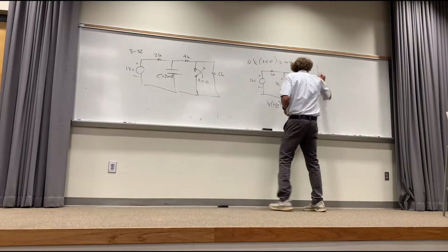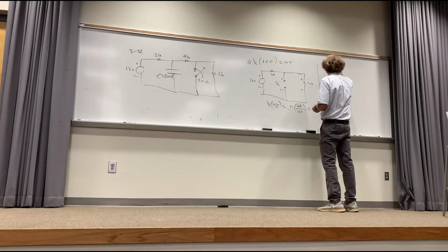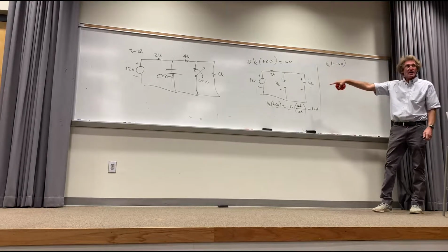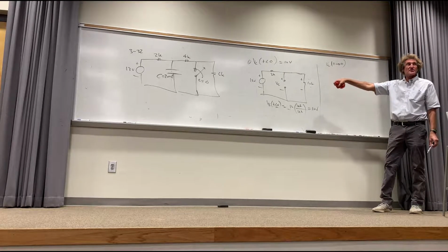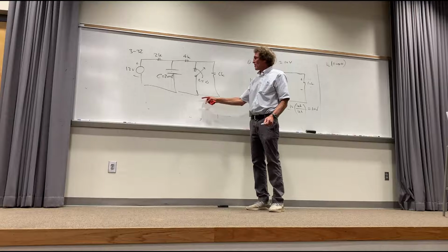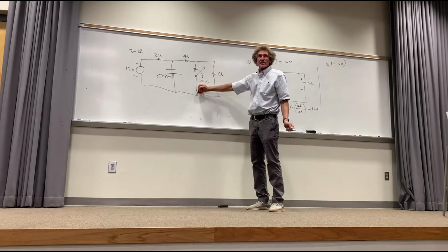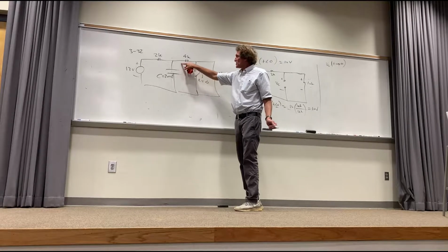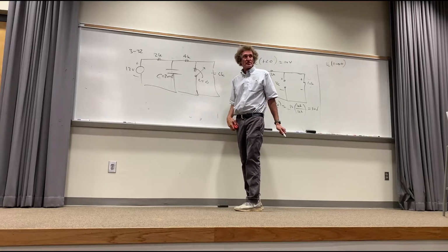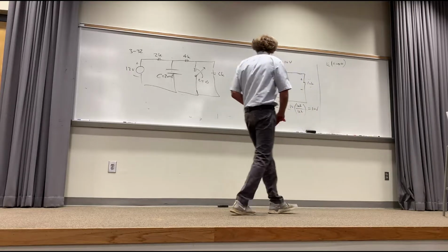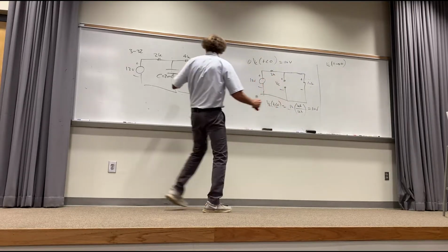The next step is to find the voltage as t goes to infinity, right? Now, I'd like to erase that board. Everybody got this? Okay? Here's what I did. For t less than 0, this switch is open, right? We can get rid of that, right? And now I want the voltage across this, which is an open circuit, right? You see how the 4 and 6 are in series? If this isn't there? Yeah. Okay, that's why. But why? Because then wouldn't these two be in parallel with this capacitor right here?